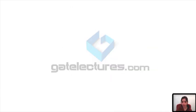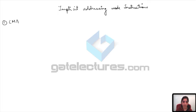So now we are going to look at some instructions from implicit addressing mode. So first instruction that we are going to look at is CMA, which is complement accumulator. Complement accumulator. So this is going to perform one's complement.